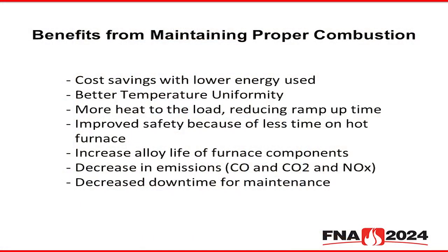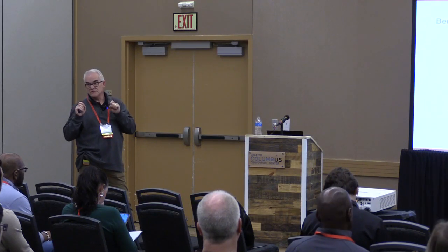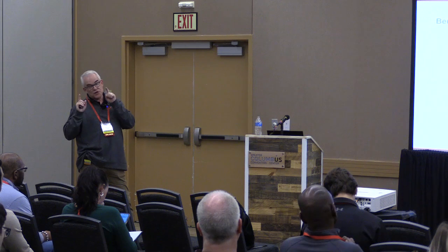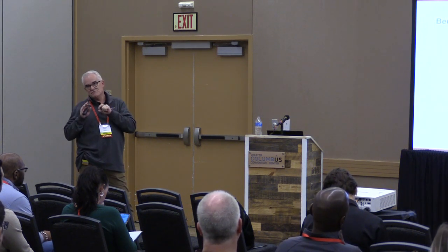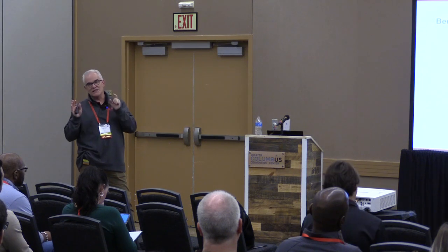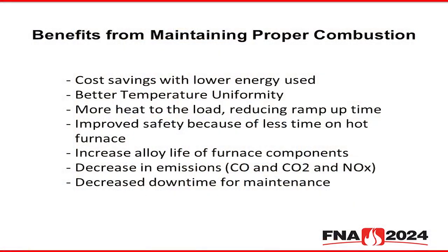Improve safety, I just talked about that. Increase alloy life of furnace components. All the alloy in your furnaces really likes it when it's not too rich, otherwise you start to carburize your alloy. Those of you that know, when you carburize your alloy, it gets brittle. A lot of us are rough on our tooling, baskets and fixturing, so as it becomes brittle and you bang it around, it breaks. Alloy's expensive. Decrease in emissions, decrease downtime for maintenance.